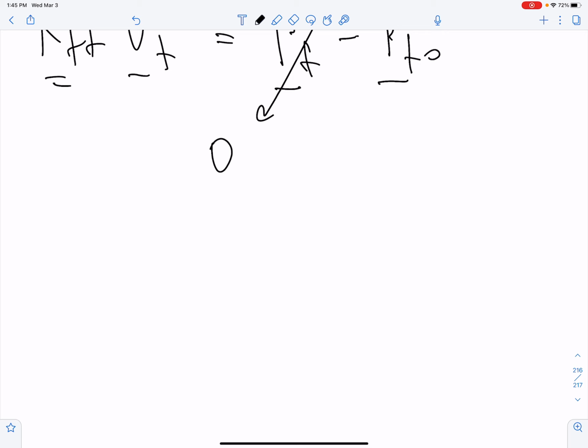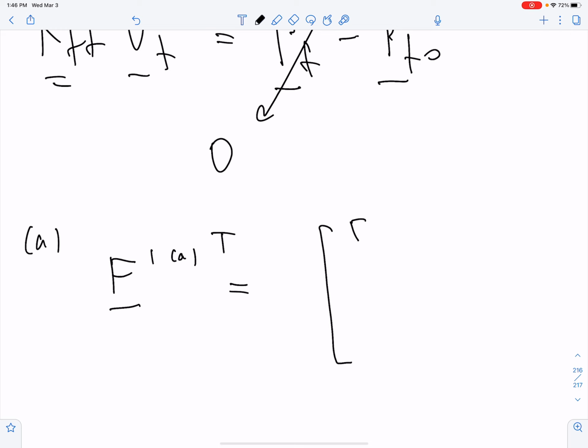Okay, and so P of 0 in principle will have contributions from A, B, and C. Right. Let's look at the contribution A. All right, and we can look directly in the local coordinate system. Okay, and we get EA alpha delta t, what we derived earlier in the lecture, 0, minus EA alpha delta t, 0.